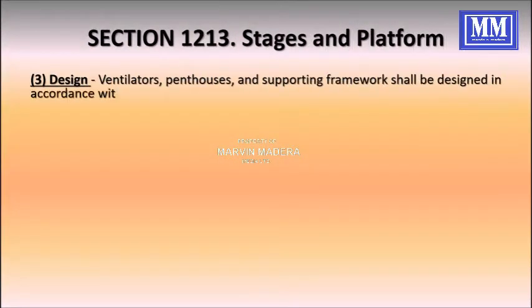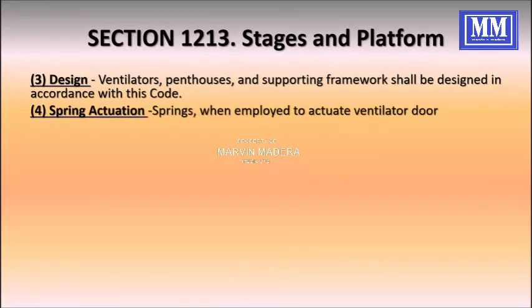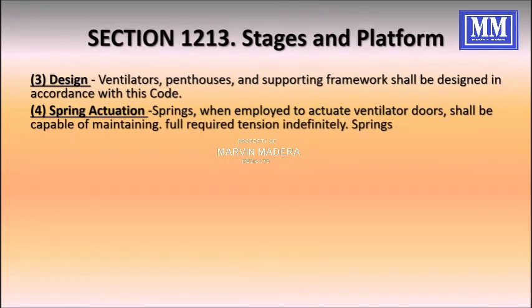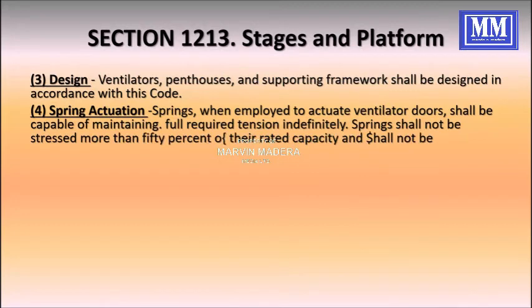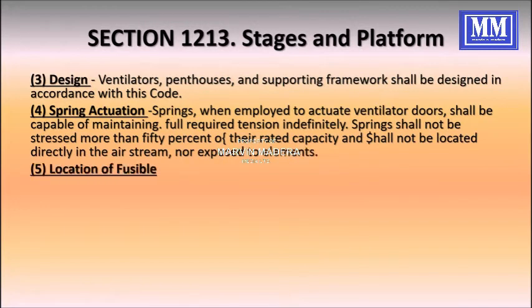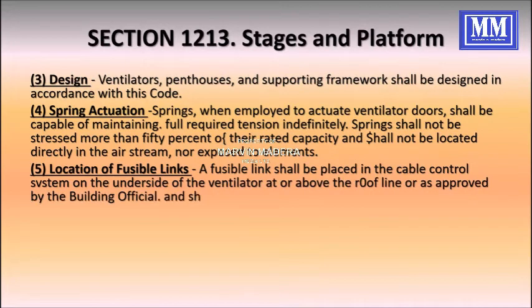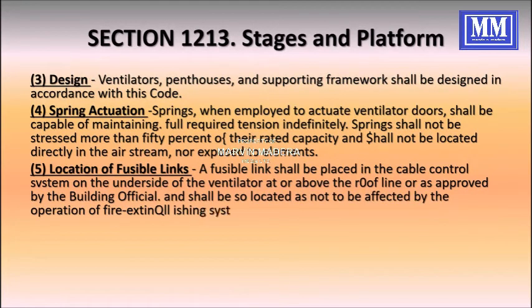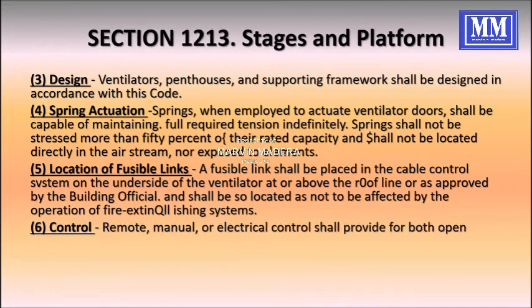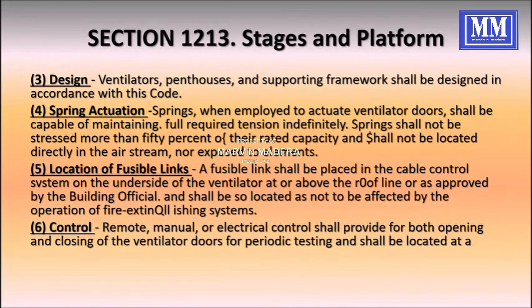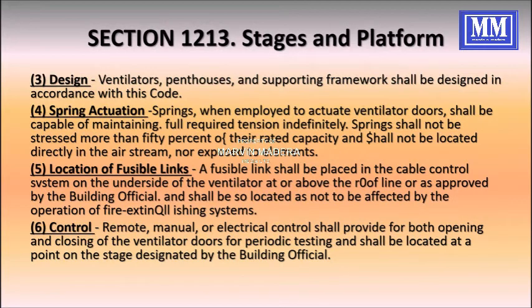Ventilators, penthouses, and supporting frameworks shall be designed in accordance with this code. Springs, when employed to actuate ventilator doors, shall be capable of maintaining full required tension indefinitely. Springs shall not be stressed more than 50% of their rated capacity and shall not be located directly in the air stream nor exposed to the elements.